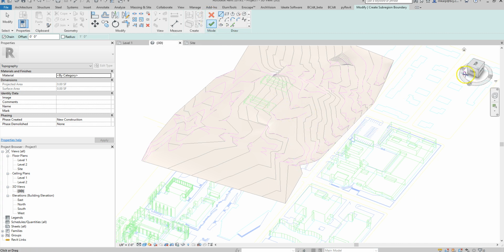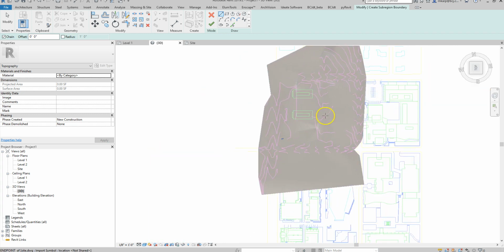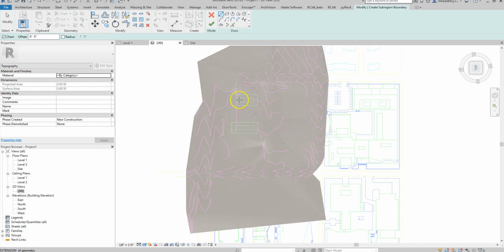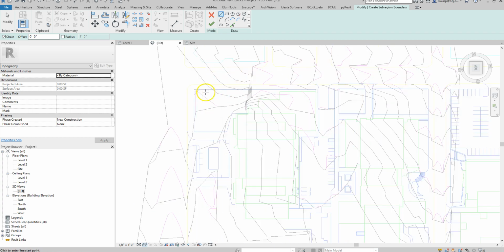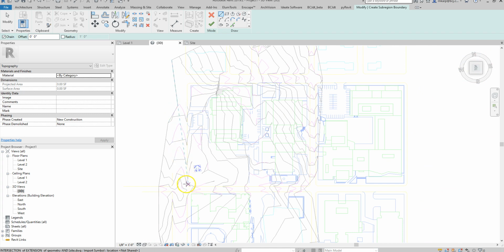So now I can select lines. So what I'm going to do is go to a top view where I'm looking down, and unfortunately we can't see the outline of our block just because this is a solid piece between us. So what you can do is we could switch it over to wireframe, and we can see the yellow line that runs around our block. So what we need to do is make a continuous line that crosses all of this and intersects the topo surface we have.